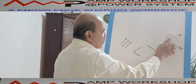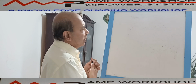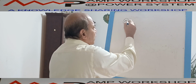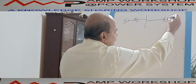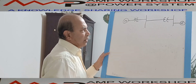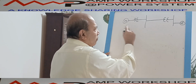So first we will calculate the short circuit current for a three phase power system when a single phase to ground fault takes place. Let us draw a single line diagram of a three phase system. Suppose there is a power system with a generator, then a transformer, then a bus bar. From there a transmission line, then a transformer, then another bus bar, and then a motor load. So this type of power system is there. I have drawn it as a single line; if we consider three phases, there will be three lines.